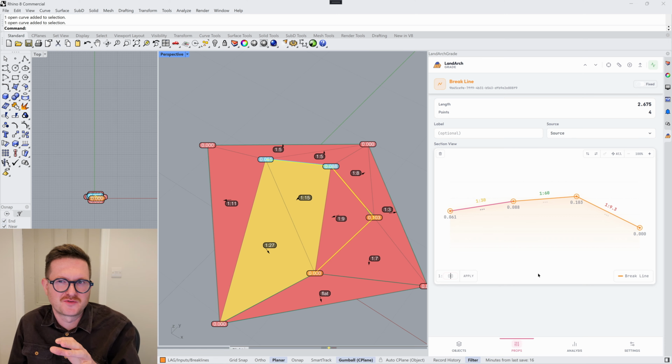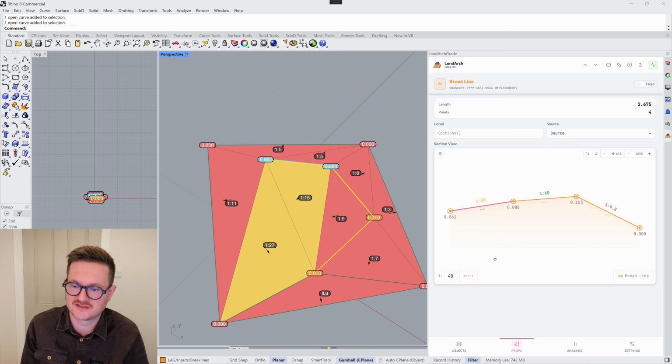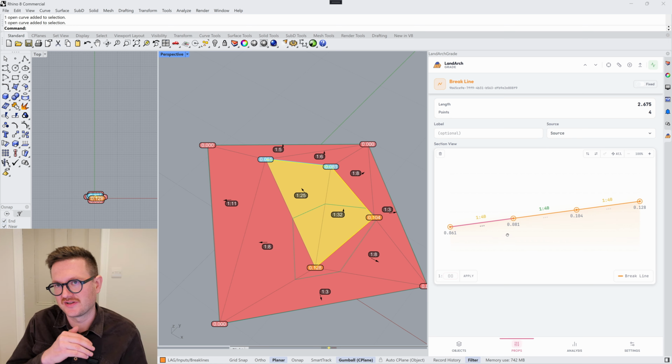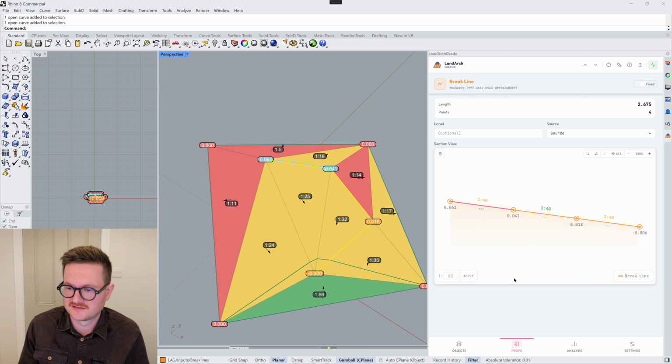I'm going to go through the more detailed parts of it, and I think they'll start to make a little bit more sense as we go down the track of complexity. But just to note down here, if you want to grade the whole thing as one grade, say 1 in 40, you can just set that and it will set the whole curve as that as well. And that notation of doing left to right works here as well. Just less than and greater than arrows on your keyboard.